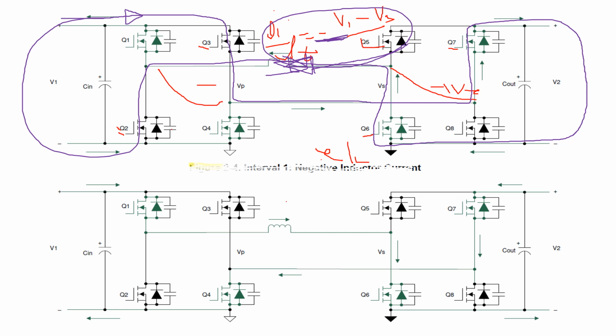So for example, this is my primary voltage, with a 50% duty cycle, so the off state will be equal to the on state. And this is my secondary voltage. It will be spaced by some kind of phase shift. It will come this way and go this way, so 50% duty cycle. So we should have something like this.